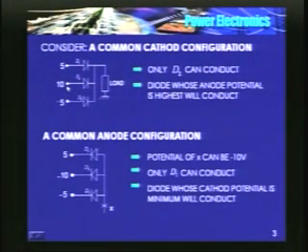Anode potential is 10 volts, cathode is 5. So voltage across the diode is 5 volts. You can't have that situation. So therefore, D1 cannot conduct, only D2 can conduct, because if D2 conducts, cathode potential becomes 9.3 or so, or 10 itself. D1 gets reverse biased, cathode is 10, anode is 5. Similarly D3, cathode is 10, anode is minus 5.